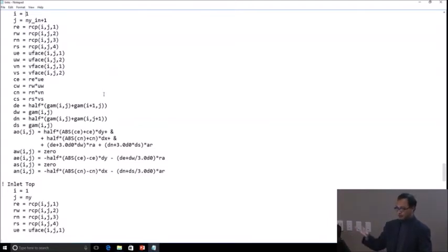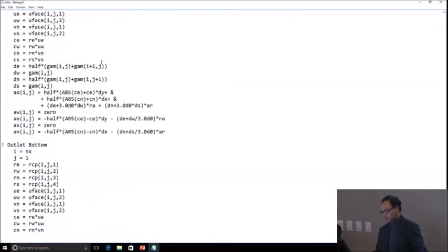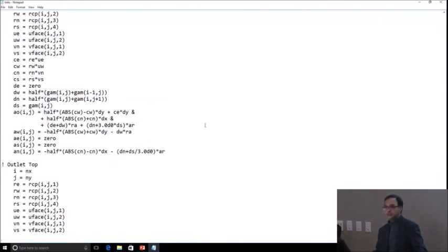Fortunately, you don't have to do this again for the v momentum or the y momentum. It's the same thing. It's the same link coefficients you're using. In fact, you don't even have to do it for the energy equation. That's what we're doing here. Remember, into this array I put in density at the face when it's the momentum equation, and density at the face times the specific heat capacity at the face when it's the energy equation. That's all. Any questions on that?